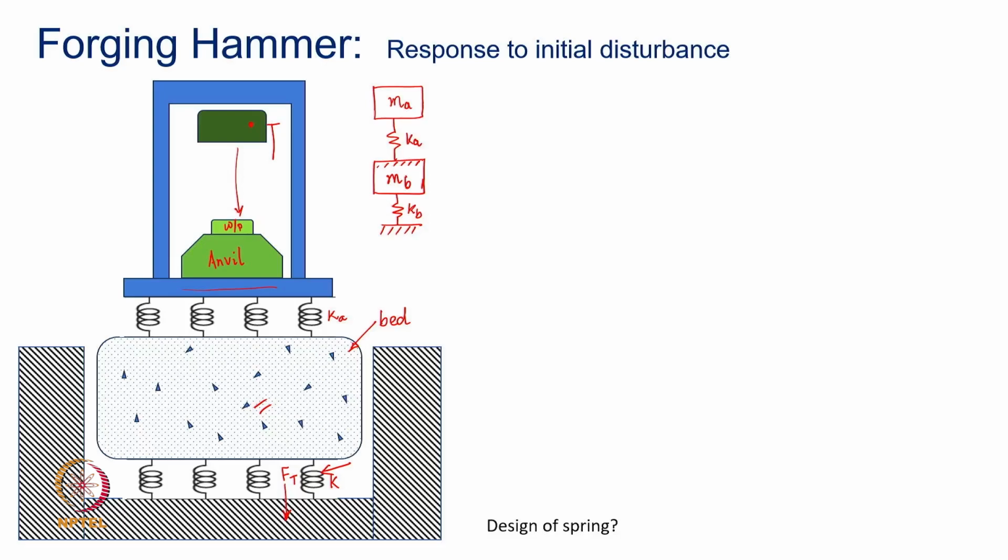Okay. And I will tell you some basic ideas as to when you really want to model a particular system as a single degree of freedom or a multi degree of freedom system. There are some basic thumb rules which you can follow, but if you want to be very accurate in terms of estimation of natural frequencies and the response, then probably you can make the system more involved and a little more comprehensive, while essentially maintaining the size to be manageable.